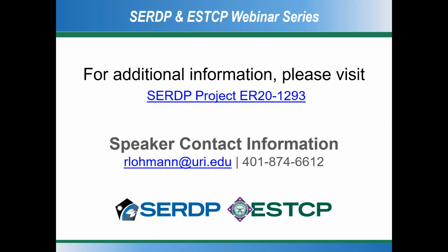Again, it depends on the question you're asking and how you want to address it. If it's about, let's say, transport within a river, not knowing the exact river in question, it's fairly simple to do the math, figuring out how much turbidity is present and how much is transported out relative to the water volume. I assume in most cases, given that most PFAS are binding to solids, but not very strongly, the flux or the mass flow with the water is going to outcompete the solids. I hope that answered the question.